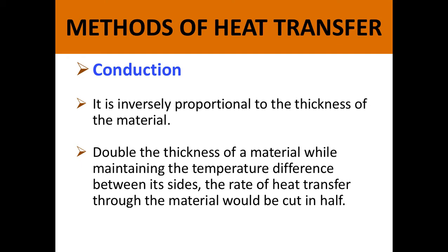Conduction is inversely proportional to the thickness of the material. Okay, the thicker the material, the lower the rate of conduction. Double the thickness of material while maintaining the temperature difference between its sides, and the rate of heat transfer through the material is cut in half.